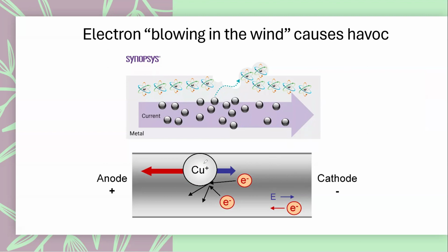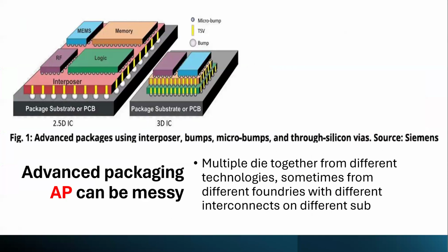It happens in the regular CMOS process, especially at the back end of line in terms of copper technology. In the metal lines, many of them, because of the very high current density going through them, you will have this electromigration phenomenon. Of course, our topic is packaging, right? Advanced packaging. And for advanced packaging, we see similar problems with more complexity.